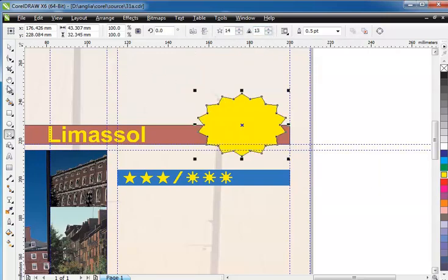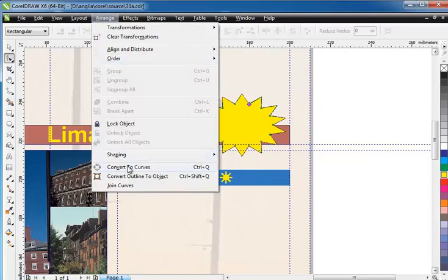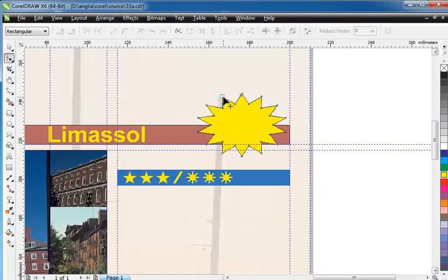Change the sharpness value to 13. We can also switch to the Shape tool and move one of these points to edit the sharpness. We can't, however, do that in the figure if it would be converted to curves. Remember about this, as it may come in handy later on. After converting the figure to curves, this object changes from a star figure to a closed curved path. Well, let's say that we need a non-standard star for this project, and leave the object as it is.